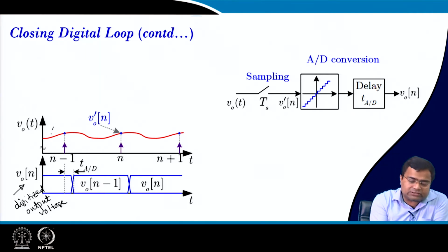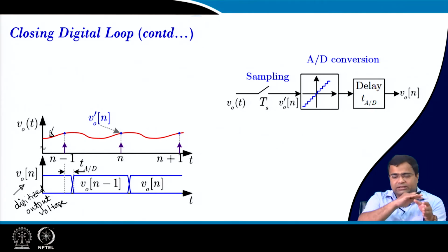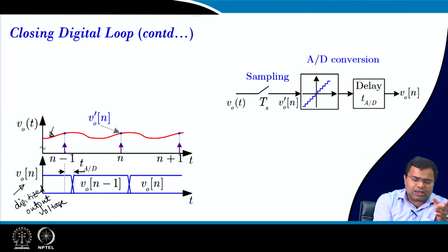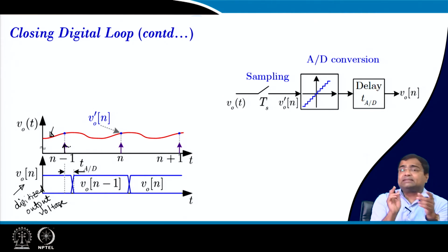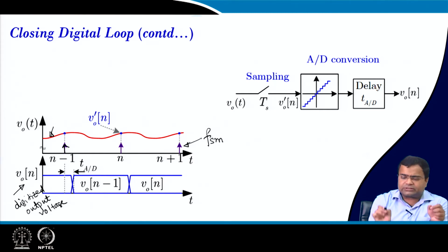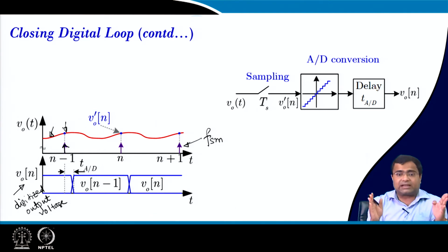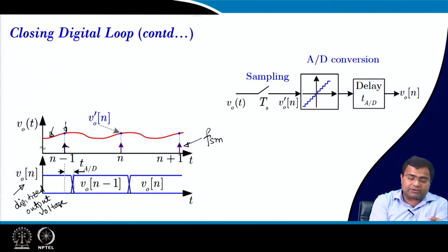So, this is the continuous time analog voltage, which is a time domain waveform, and suppose we have sent a signal, because ADC requires a clock, that means what clock edge you want to sample. Suppose this is a sampling command, this is let us say our sampling clock. Suppose you have sent that I need a sample here, but because of the conversion time this data will be available after a certain time. So, this duration is the conversion time of the ADC.